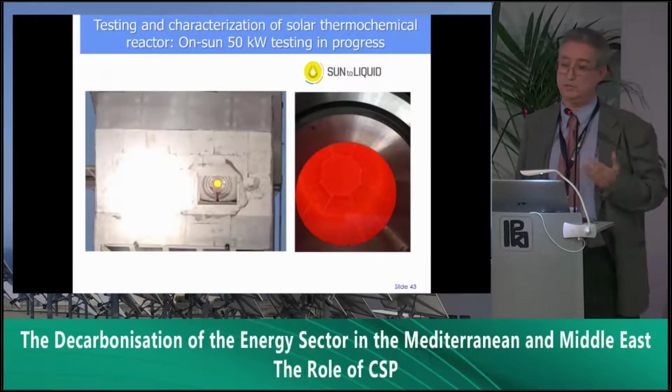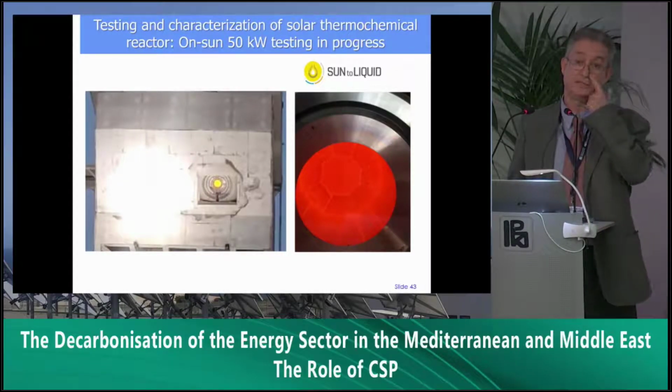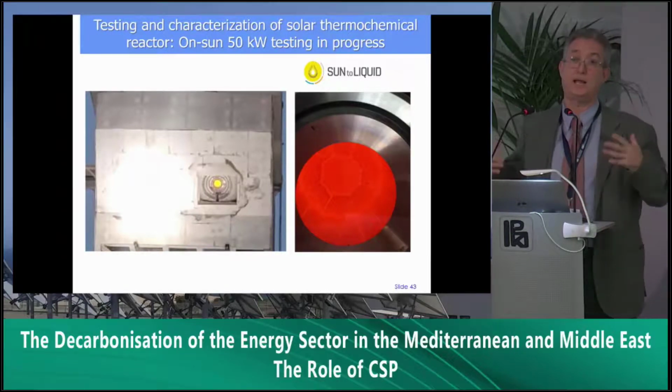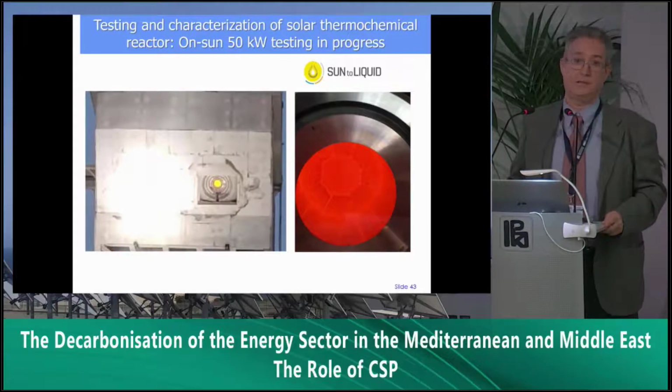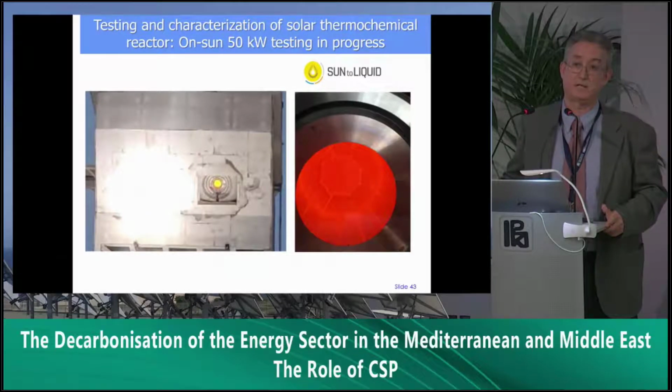For example, in our project Sand to Liquid, there is a specific task dedicated. Abengoa is involved, in fact, in the DLR and some partners discussing how to scale up this kind of solution. And scaling up is not clear. In fact, most of the current solutions involving fixed bed reactors, for example, are difficult to scale up beyond a few megawatts thermal.